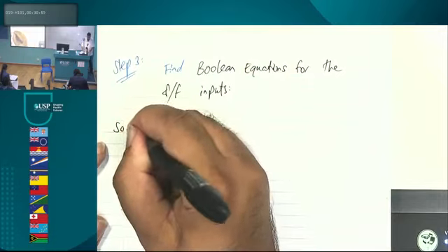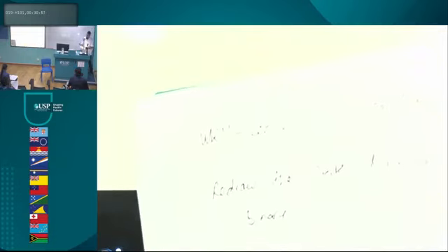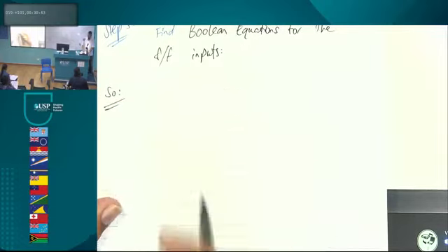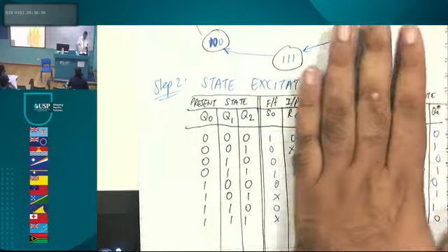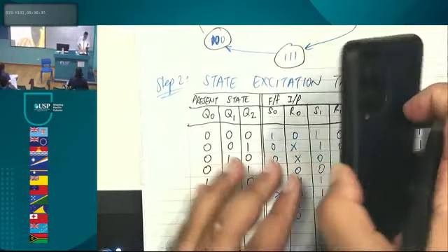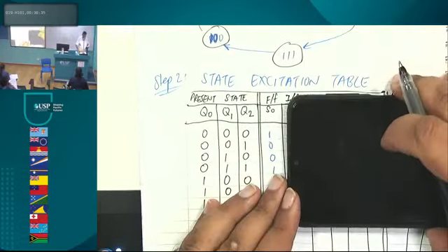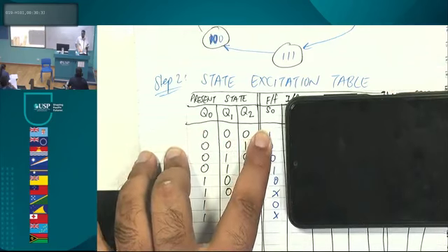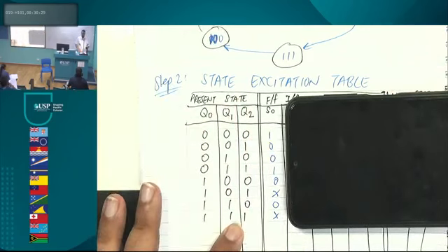Let's start off with, what was it we started off with? S0. So how many inputs, guys? If we look at this table, we forget about all of these. So it's just a 3 input and 1 output. How are you going to plot that? You're going to use a Karnaugh map.